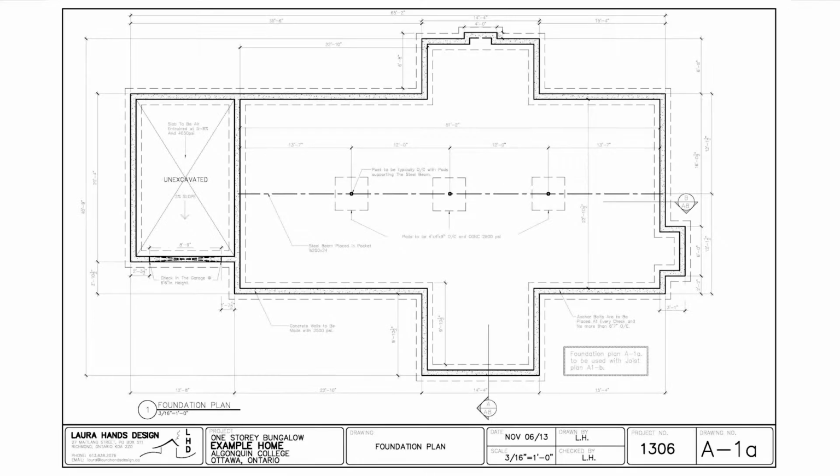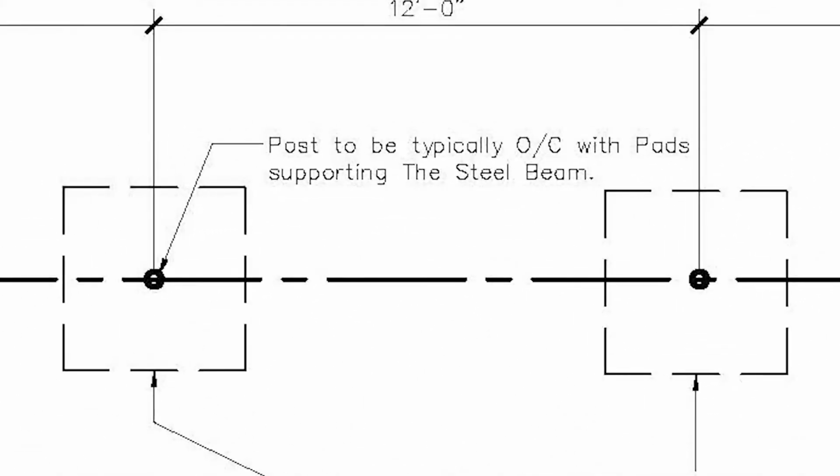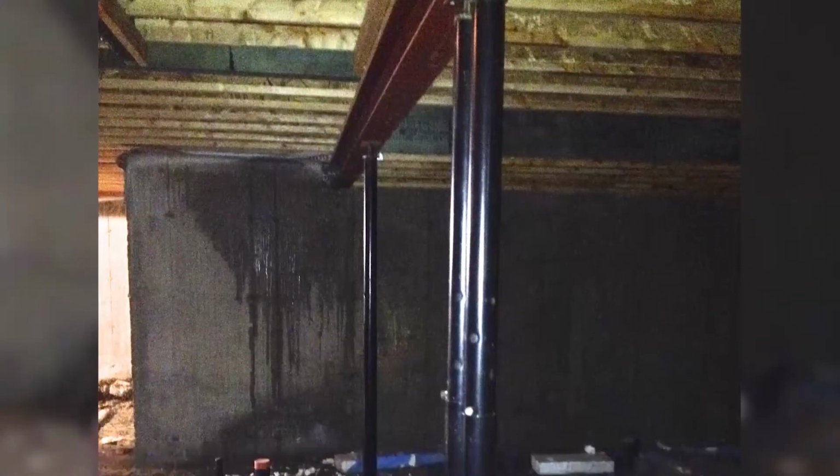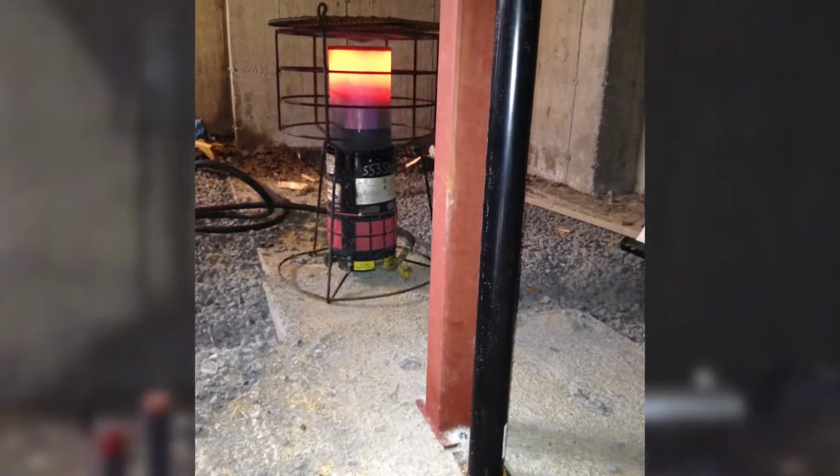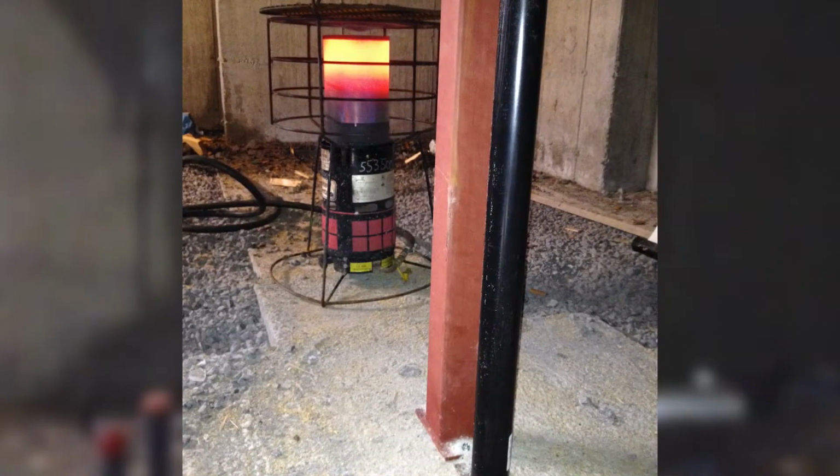Telepost. These circles in the center of the pads represent typical metal posts. Teleposts are the steel posts that are placed on top of the concrete pads, which hold the steel beam. In some cases, teleposts are temporary and can be replaced with hollow structural steel.